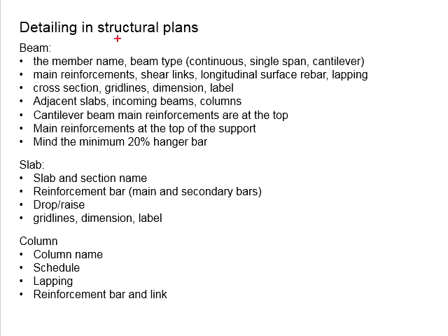You need to be careful with the adjacent slab, whether there is one slab adjacent to the beam or two slabs adjacent to the beam, or the beam itself is alone without being attached to a slab. And this will be reflected in the detailing.